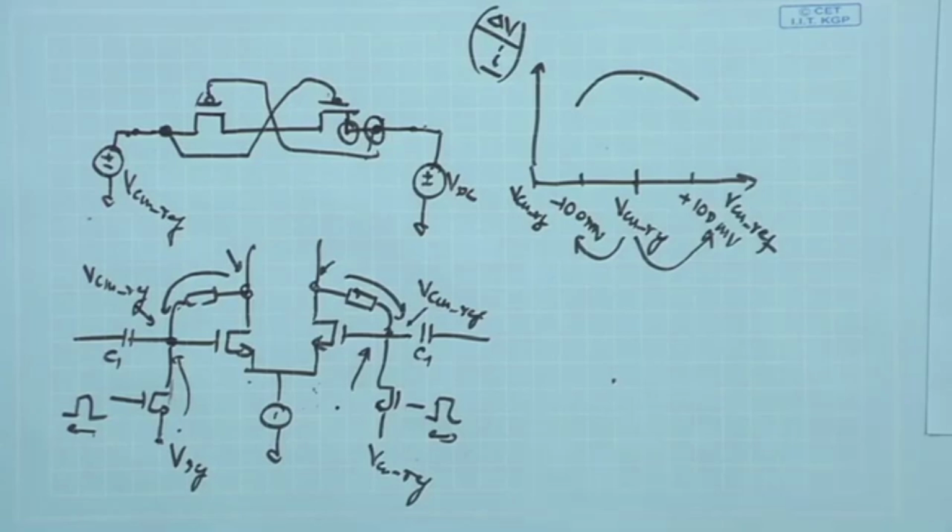It should be 1 second approximately. Because if you remember, we used this in our earlier simulation when we did not consider the chopper operation and all. If you are just looking at the low cutoff frequency of around 0.5 hertz to 1 hertz to allow our signal content to pass, in that case the cutoff frequency was chosen as around 1 hertz or lower, close to that. So accordingly, the RC time constant will be close to that.